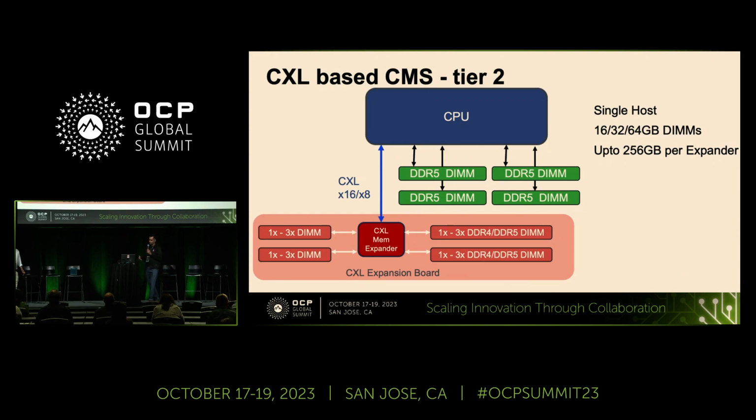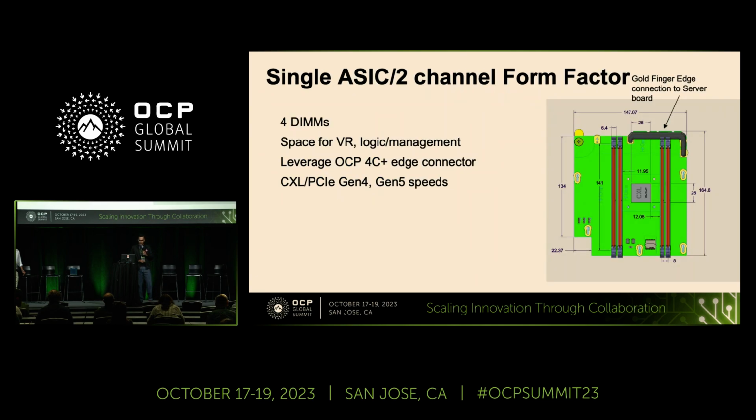We have a simple memory increment with the CXL. So this is the first form factor where we are able to use the existing DIMMs and build a memory expansion. We tested this last year, and we were able to show that the performance is on parity with some kernel transparent page placement. And with the edge connection, we can go to PCI Gen 5, and that's about where it saturates.